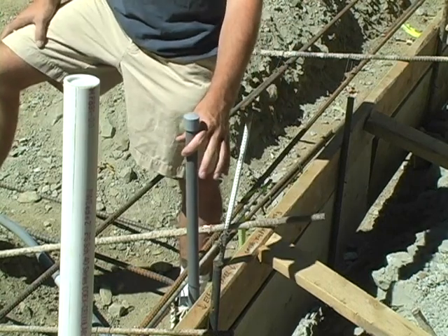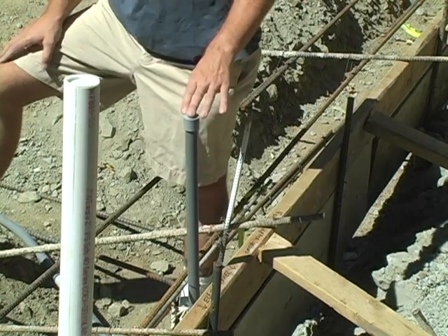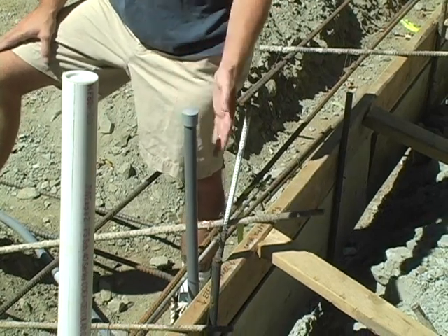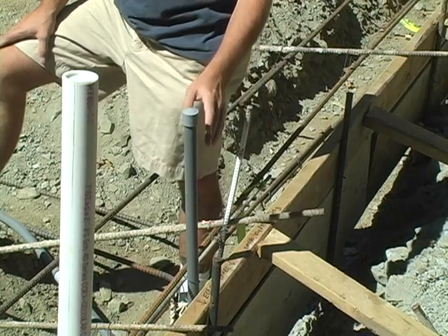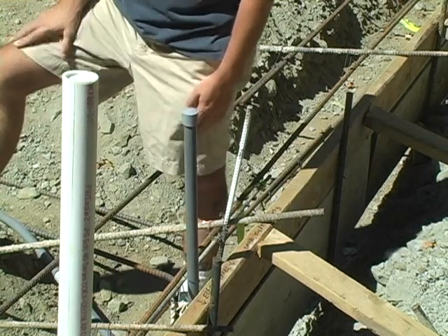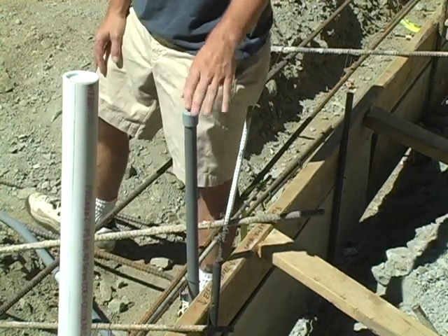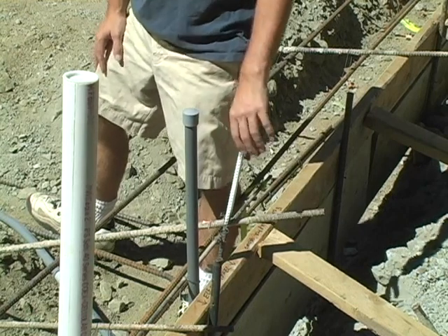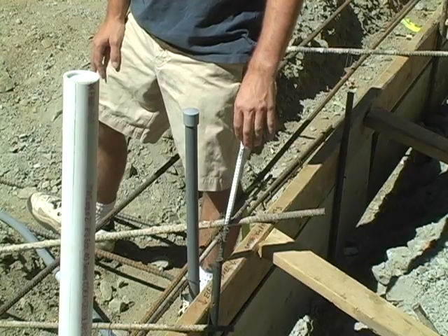We've also run a piece of conduit here that will run out as a home run to the electrical panel down in the slab. And we can also go up the wall and out into the roof line, but there's some places where it's actually going to be easier to run a conduit down through the bottom of the slab. Now this doesn't have to end up buried too deeply in the slab, it just needs to go down and be out of the way of the insulation and other materials so that we can keep our insulation flat before we do our pour.